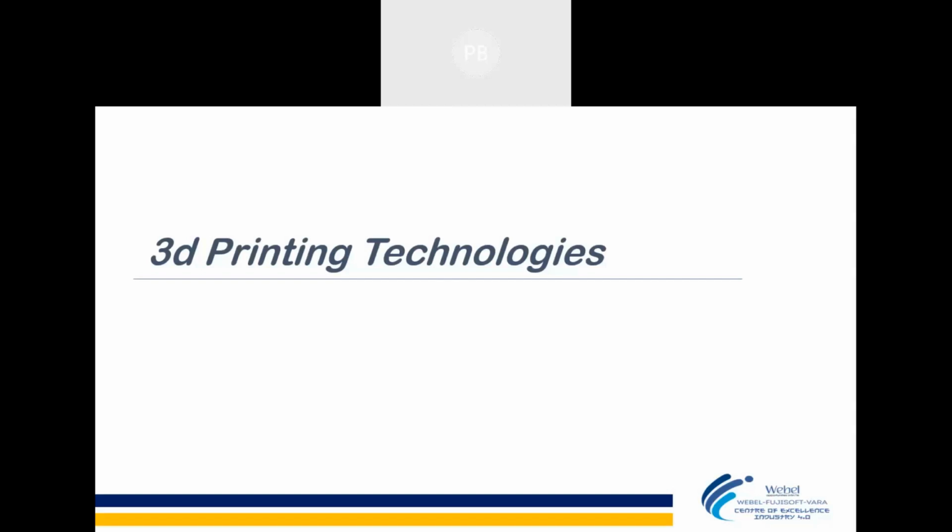This layer by layer sticks up, but it only provides a certain level of strength unless the force is acting parallel to the layer direction. If your layer is deposited in a flat direction and your force is also acting in the same parallel direction, there is a chance that layer by layer will come apart. The part will not be broken, I can say, but the layers will be separated. That can happen. That is also a disadvantage.